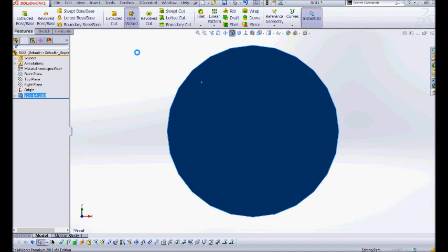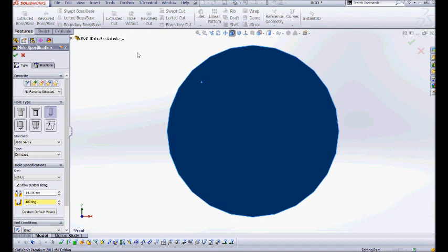Okay, we're on page 175. We're going to place a hole on the front view. So one of the ways we can orient to front view is we can come up here and select this little drop down, and select front view. Shortcut is Control+1. So if you do the Control key +1, that will also give you a front view.